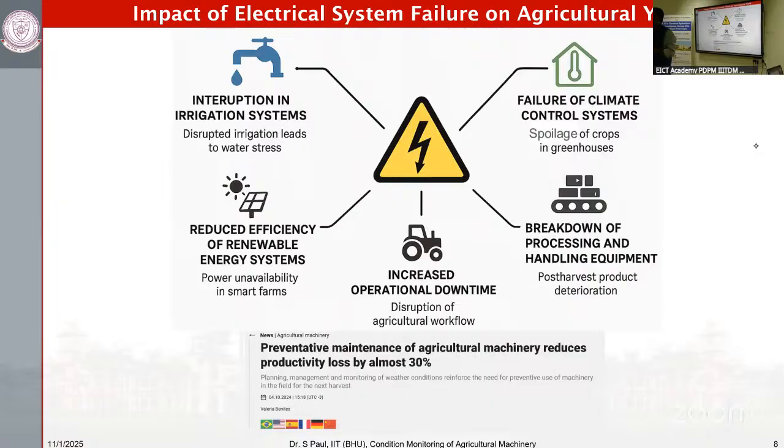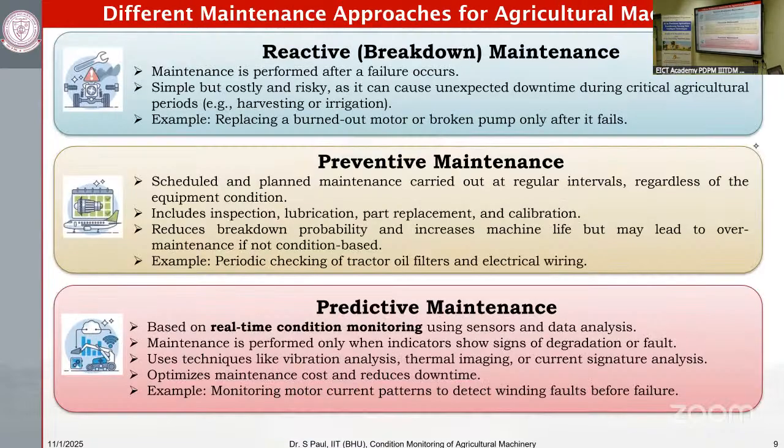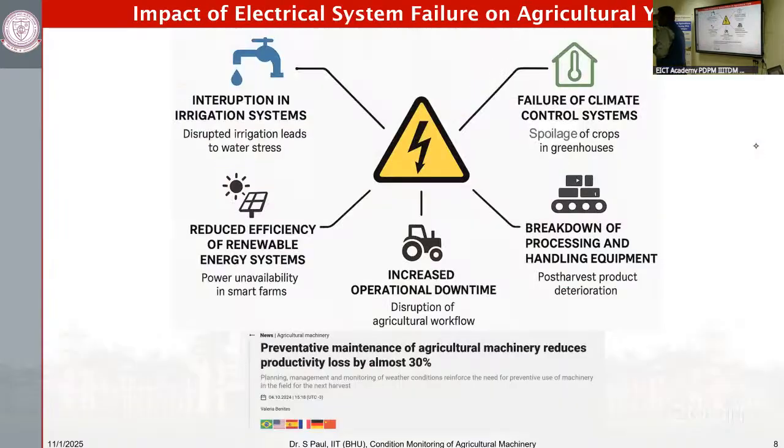So previously, what had been scheduled for UP, they had not informed to the power grid. They knew that they have to consume almost 10 times what they have informed to the system. So what happened? They started consuming, and after that one line failed, but they didn't turn off their system. They didn't shed their load. So the first line got out of order, then the second line, and that actually made the entire western grid fail. Your entire Maharashtra, Rajasthan, and Gujarat power supply went dark.